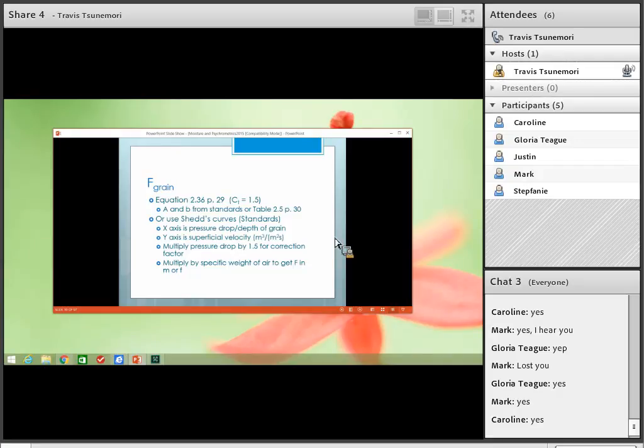That is the volumetric flow rate of the air divided by the cross-sectional area of the bin. It's usually expressed in meters cubed per meter squared second, where I've usually seen them leave in the meters cubed per meter squared instead of simplifying it to meters, so that you realize it's superficial velocity and not just velocity.